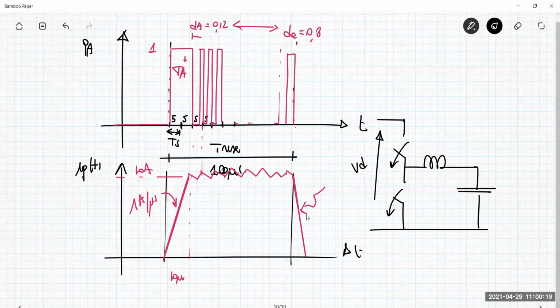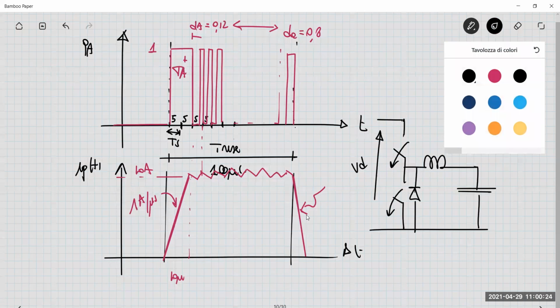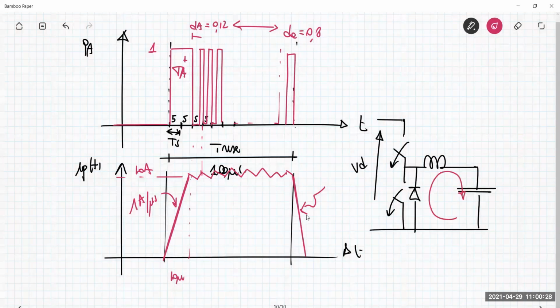They are left open. Here we have a diode, which is the freewheeling diode for the current. The current is positive here, so it flows through the diode. And so the voltage drop across this diode is, let's say, the capacitor here now has a voltage VP, which is the maximum voltage, because now the voltage across the capacitor is, say, 200 volts. Now it's fully charged.